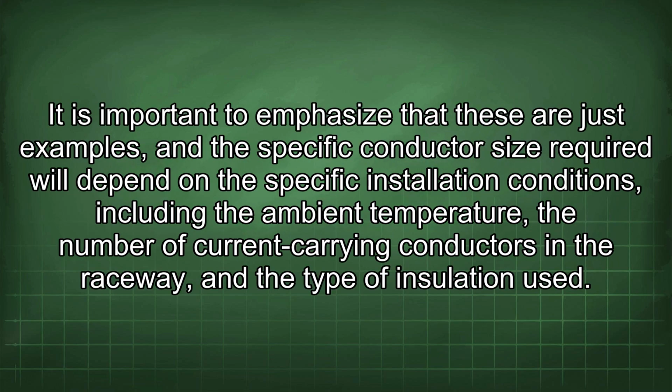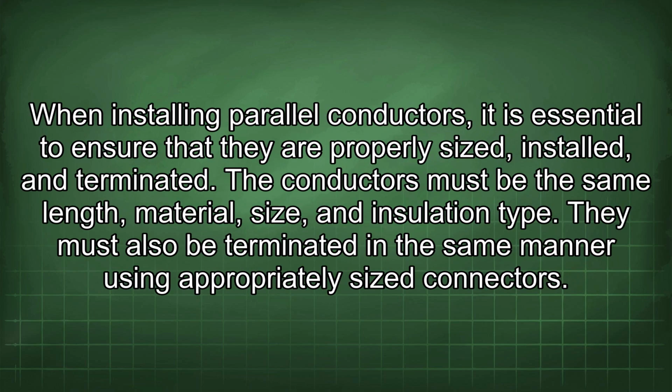It is important to emphasize that these are just examples, and the specific conductor size required will depend on the specific installation conditions, including the ambient temperature, the number of current carrying conductors in the raceway, and the type of insulation used. When installing parallel conductors, it is essential to ensure that they are properly sized, installed, and terminated.